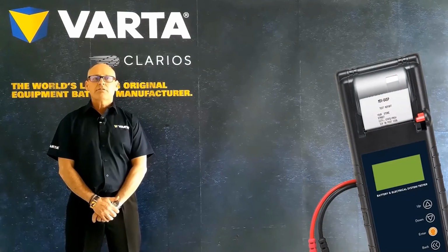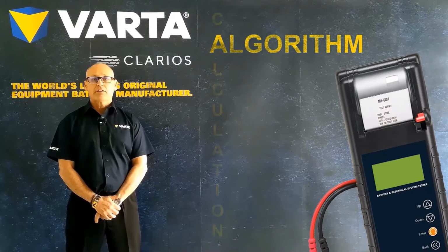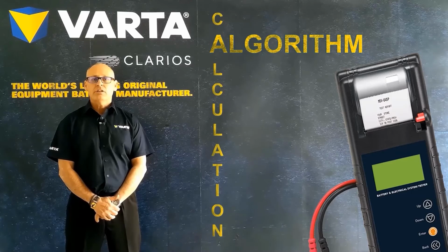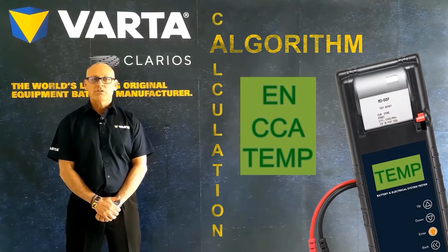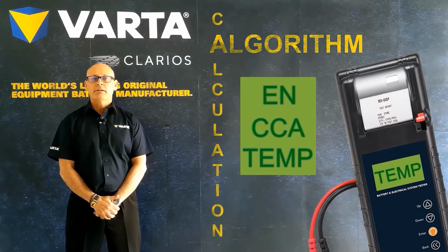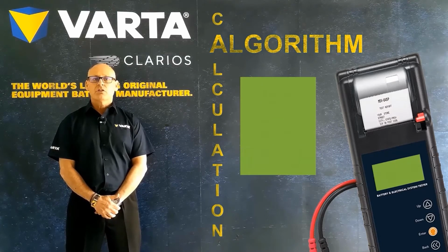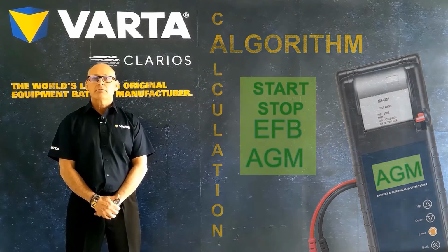This detail is very important because each quality tester has set algorithms and calculations for each battery technology, EN rating, CCAs, plus don't forget the temperature, which has a dramatic effect on the results. A good quality tester with a printout is always recommended, but it must include start-stop, EFB and AGM within its menu. So let's have a look at testing a battery.